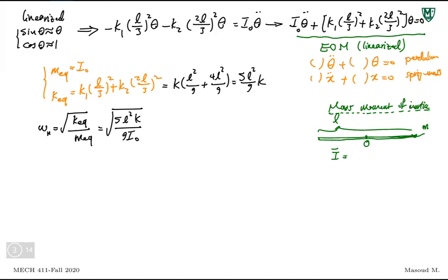Area moment of inertia, the concepts are the same, but mass moment of inertia is what we use in dynamics, while area moment of inertia is mainly used when you're studying solid mechanics. So the mass moment of inertia, 1/12 is on point. Is it 1/12 ml squared? Yes, exactly, Michael. m L squared.